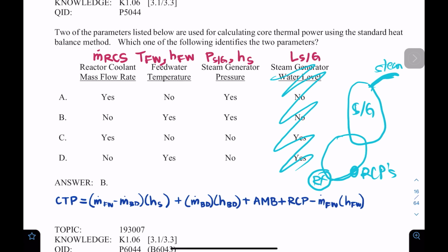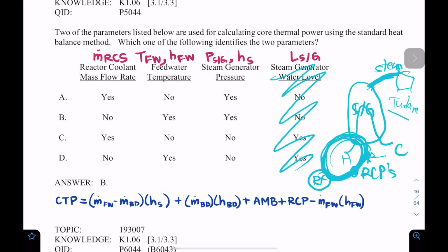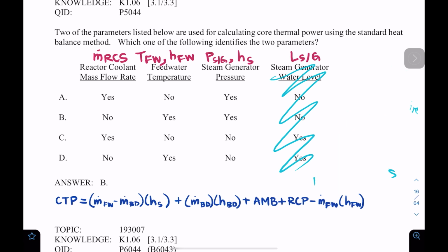And the reason that we don't count it: remember when we removed the letdown from our system, because that was part of the control volume system. That's the part that is feeding this part in here to make sure that we cool the water. So this one is the hot leg and this one is the cold leg, and this is the steam that we send to the turbine. Yeah, my drawings aren't the best, but you get the idea from that, right? So that means that the flow rate from my reactor cooling system is not part of this formula, because it's part of my primary.